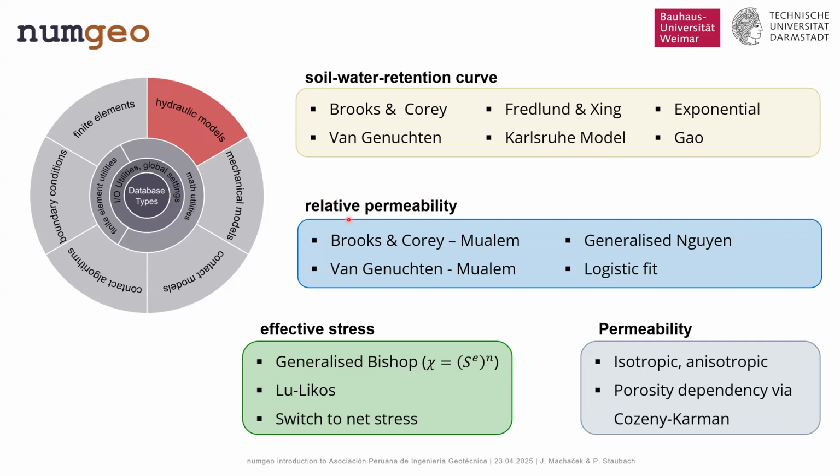On top of that, we implemented different models to take into account the decrease in hydraulic conductivity once a soil is getting partly saturated. For that, we have implemented industry standard models like the Brooks and Corey model, the van Genuchten model, and also the NUMGEO model, which are quite widely used.